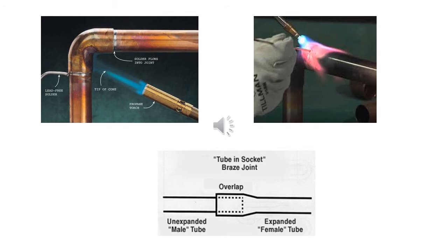Soldered joints depend on capillary action, drawing free-flowing molten solder into the gap between the fitting and the tube. Flux acts as a wetting agent and when properly applied permits uniform spreading of the molten solder over the surfaces to be joined. What do we mean by capillary action? To put it in very simple terms, it is the ability of a liquid to rise into a narrow gap or passage against the force of gravity.